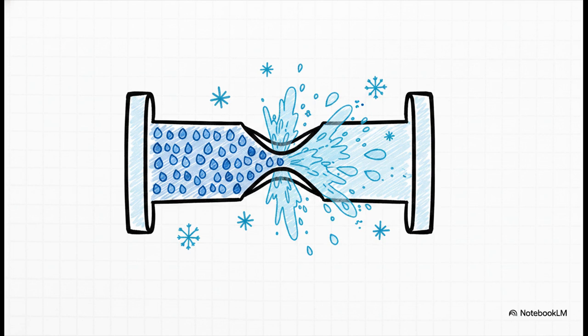The refrigerant is a liquid again, sure, but it's still under really high pressure, and it's not quite cold enough to cool your house yet. It travels back inside and hits a really critical component, the expansion valve. This little valve forces the liquid through a tiny opening, which causes an abrupt and massive drop in pressure.